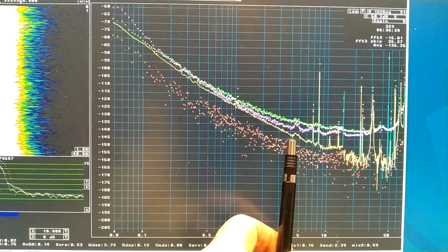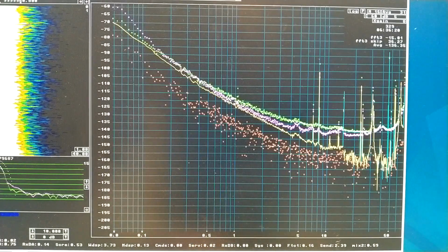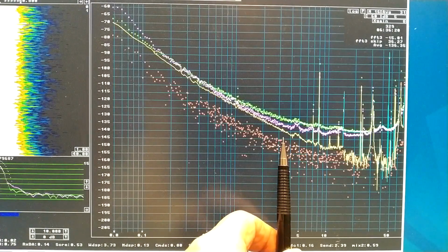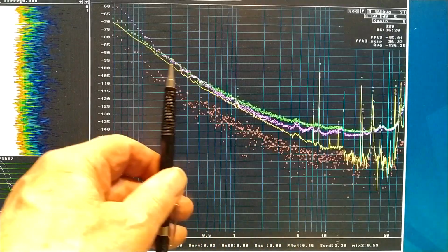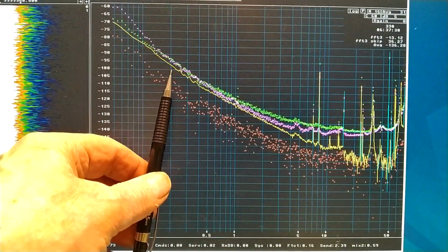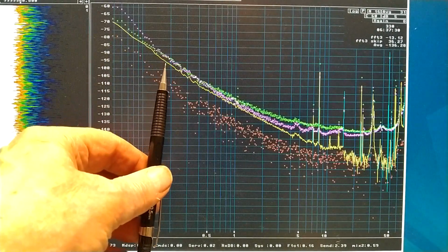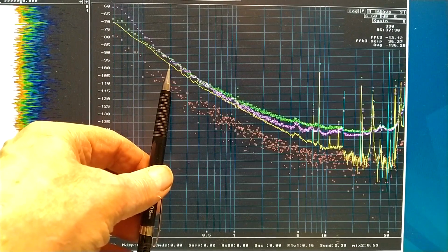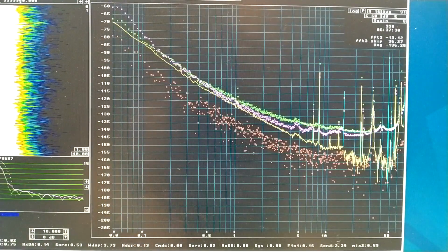At 4 Hz, sometimes at 5 Hz, this structure that I don't know what is causing it is degrading the measurement. So I think I should not go higher than about 3.5 Hz. And then at the low side, starting at 0.2 Hz means I don't miss so many data points. So from 0.2 up to 3.5 will be what I think is optimum.